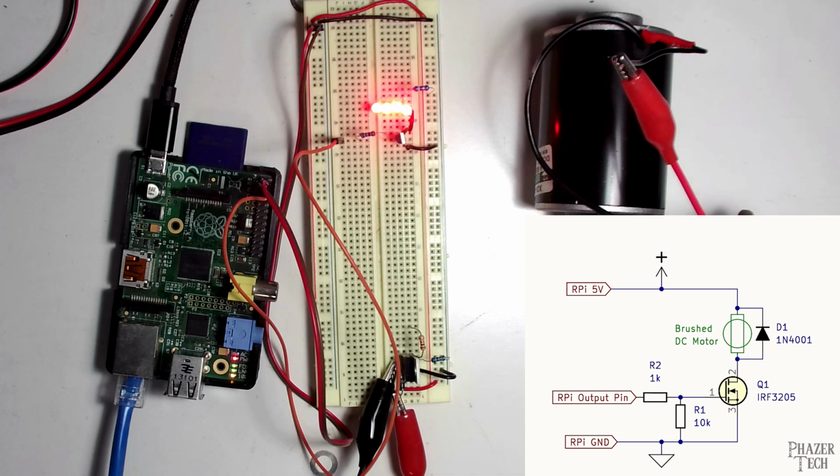All right, so now we can turn this on. And oh yeah, it only draws about 200 milliamps when running at 5 volts. The higher the voltage, the more current it will draw. Now, since it only draws around 200 milliamps at 5 volts, I can actually power this with the Raspberry Pi's power supply. So that's what I'll do first, and then afterwards I'll use a different power supply running at 12 volts so it'll drive the motor faster.